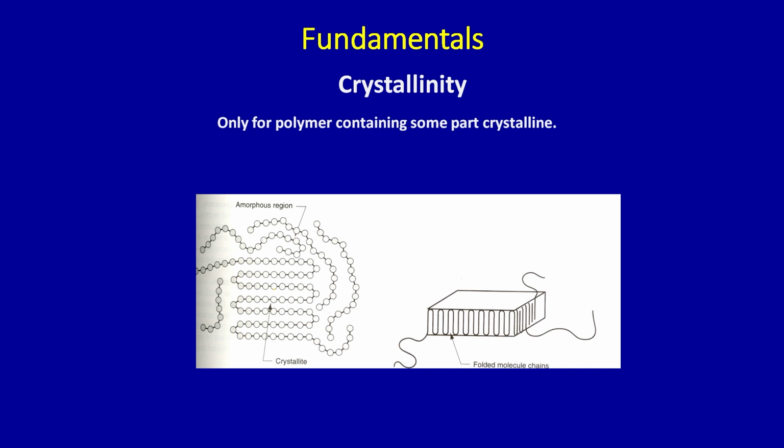Crystalline materials have a definite order of arrangement of atoms, and that is what you see in BCC, FCC, HCP structures, so that is a defining feature of any crystalline material, and that is borrowed here. Here you can see chains are arranged in a very definite way, parallel to each other and in an orderly manner, that is why they are called the crystalline part of the polymers. But if the chains are in a haphazard way, then it will be amorphous polymers.